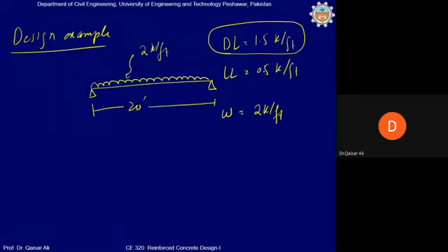After the crack, soon after the crack will propagate toward the top, and the beam will abruptly break into two pieces. There will be a brittle failure. That is why, if you want to design the beam as a plain concrete beam, then we will not allow the crack in the beam. Clear? So, which means that we will design the beam corresponding to stage 1. Clear?